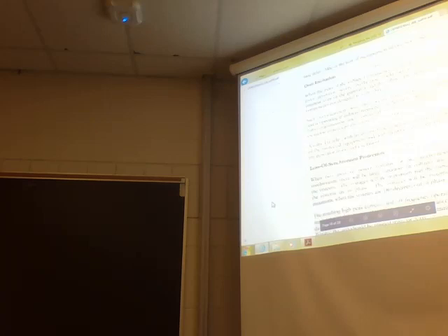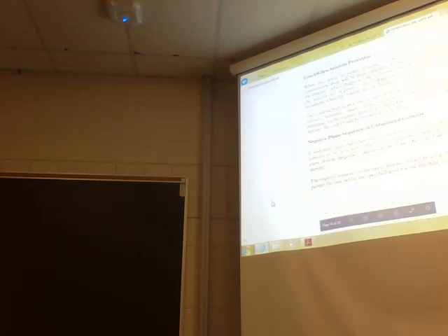Another type is loss of synchronism. When two areas of power systems or two interconnecting systems lose synchronism, there will be large variations in voltages and currents throughout the systems. The voltages will be maximum and the currents minimum when the systems are in phase. The voltages will be minimum and the currents maximum when the systems are 180 degrees out of phase.